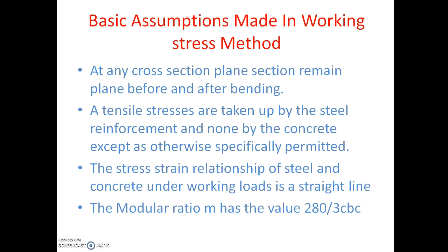At any cross section, the plane section remains plane before and after bending. Let us take a rectangular cross section. After bending, the particular section also remains plane. The tensile stresses in the concrete are taken as 0, and the tensile stresses are taken up only by the steel reinforcement and none by the concrete, except as otherwise specified.